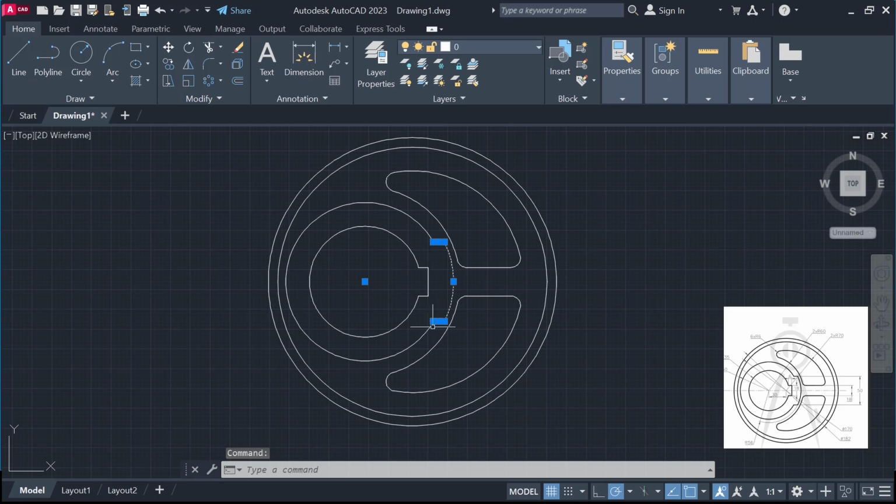Alright, so this is basically it here, but if you want you can go further and combine the shapes to form one image. We press J. Join only works for interconnected shapes or loops. Yeah, you can say a loop. The ones where you can follow a single path around those shapes, the join command will work. That's something I usually like to try. Just select or press J, and then it does the work for you.